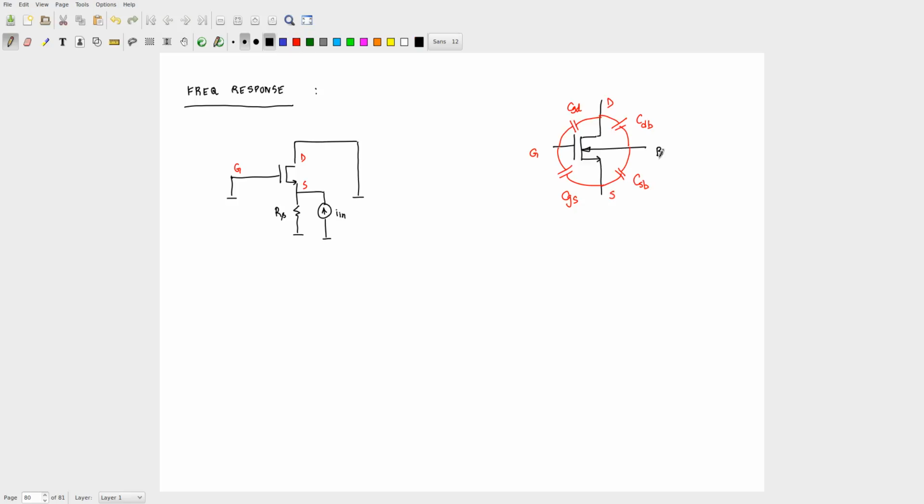In this circuit, bulk we are going to connect to gate. Yeah, because bulk is connected to ground, right? It so happens that gate also is connected to ground. So correct, what she is saying is right. Bulk is connected to the most negative point of the circuit, right? And in the incremental circuit, what is the most negative value? 0. So it's connected to 0. For this course, bulk is always connected to 0. Okay. In more advanced courses, people do interesting things. Let's not go there. That is correct.